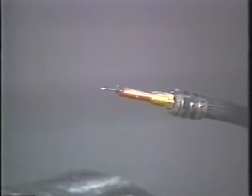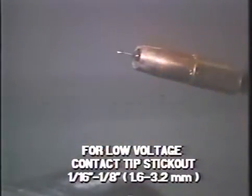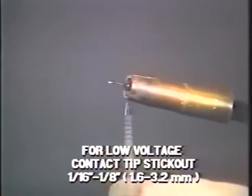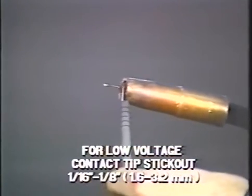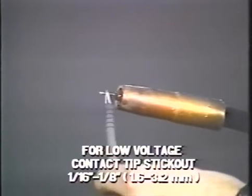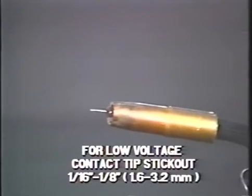So the critical thing on short circuit welding is contact tip about 1/8 of an inch outside the nozzle, and the wire stick-out about 3/16 of an inch from the end of the contact tip.